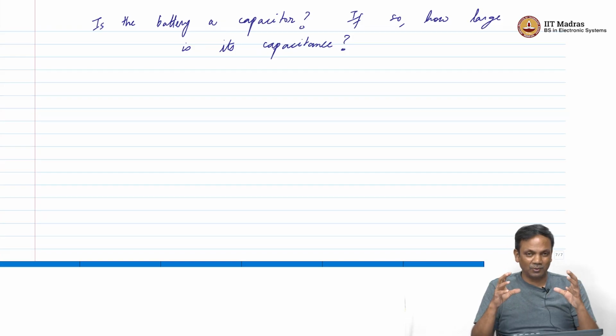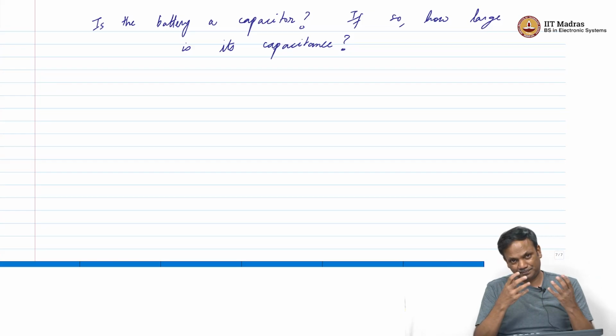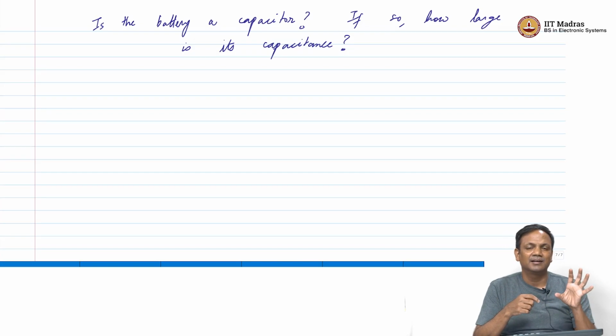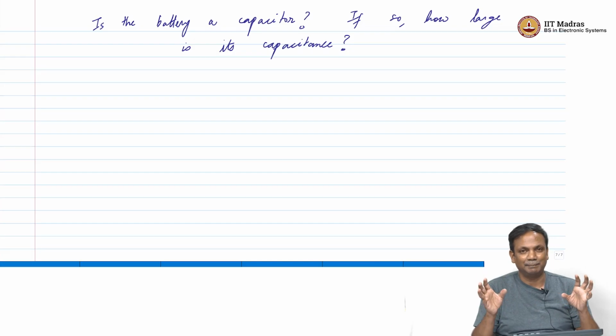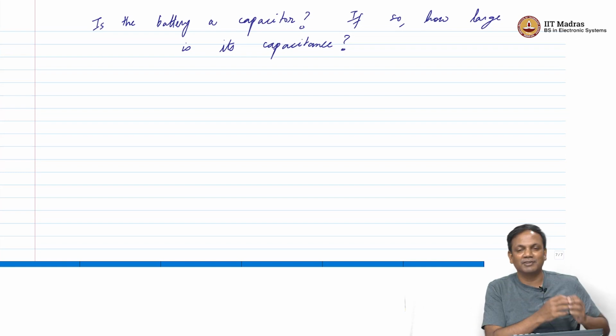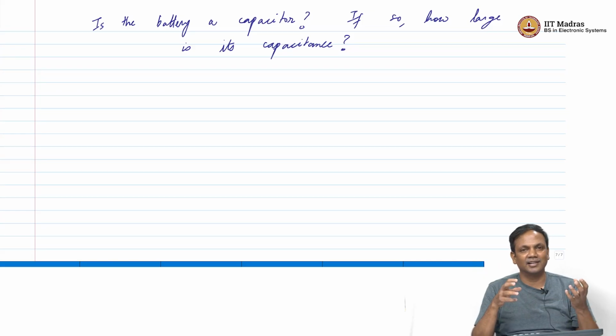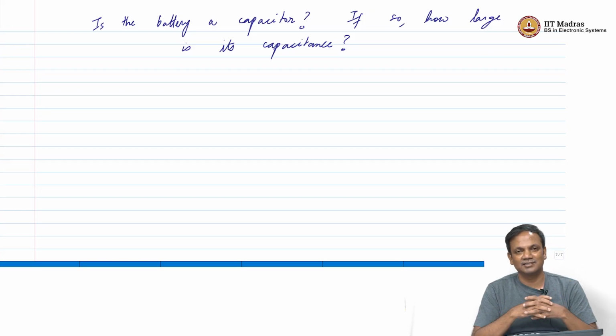So, the milliamp hour or ampere hour is a unit that is used quite frequently for the battery. And you think about what unit is that, right? It is essentially current multiplied by time, and current multiplied by time is charge. So, what they are saying when they say 1000 mAh, 5000 mAh or 5 ampere hour is essentially telling you this is the amount of charge that that battery can hold, or that capacitor can hold when it is fully charged.